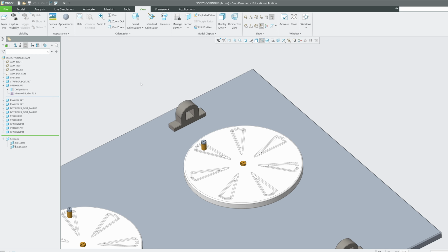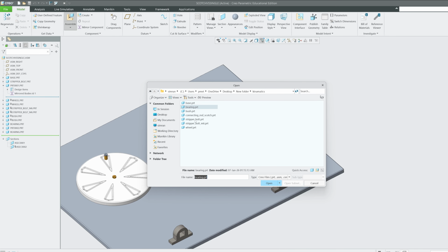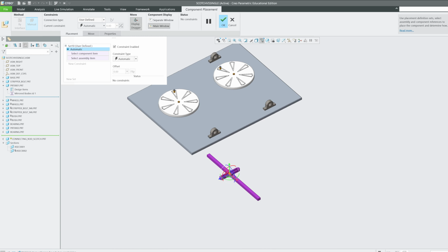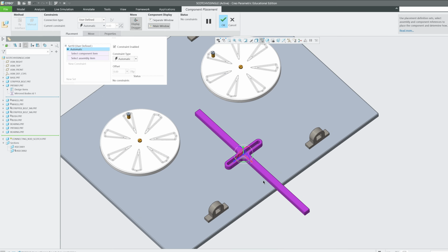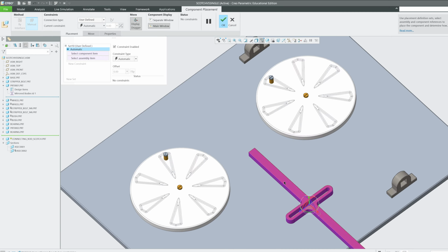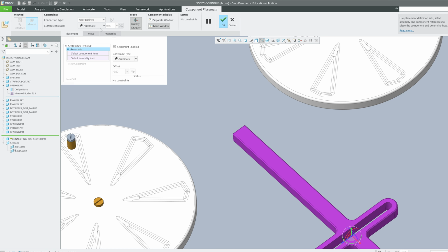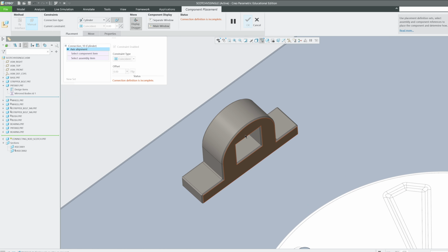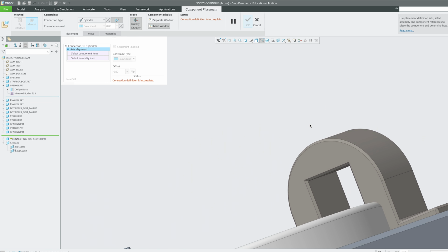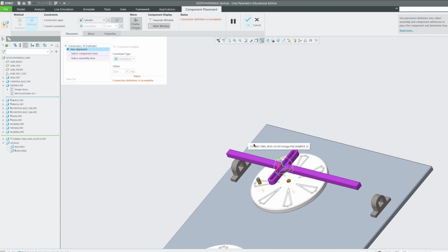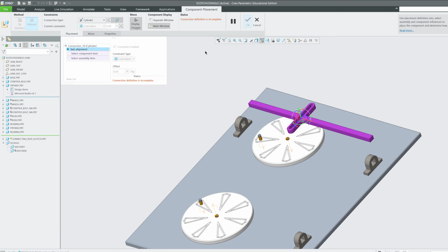Now the interesting part came, like how we are going to assemble it. So for that, first of all, let's add it here. There will be multiple joints that we need to create. I'm also thinking of okay, so this side is long, this side is short. First of all, let me add cylinder joint here. Now I'm going to select this side and probably the top side. Okay, so it needs axis to axis alignment, huh? Okay, for that probably I need to create one axis actually.